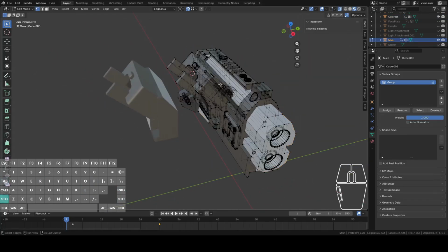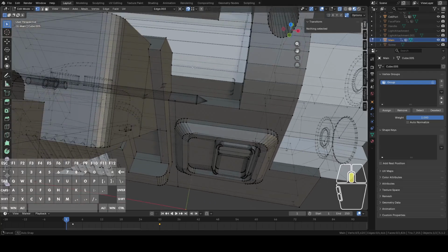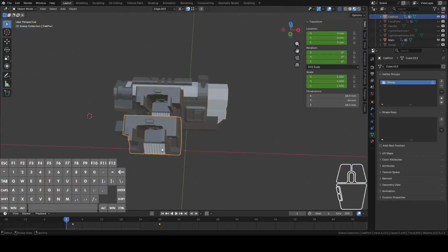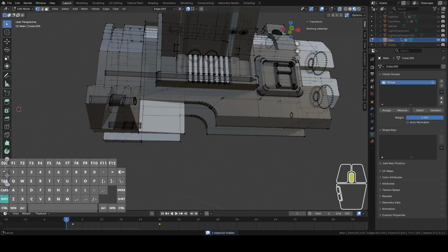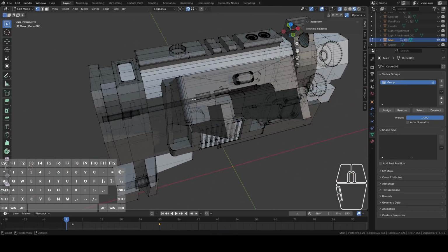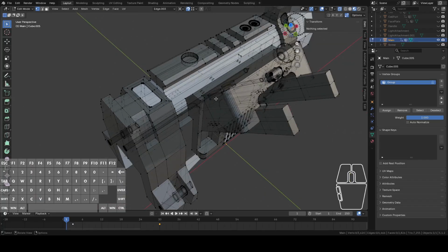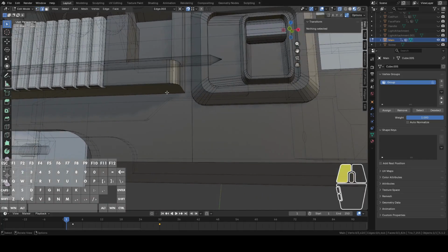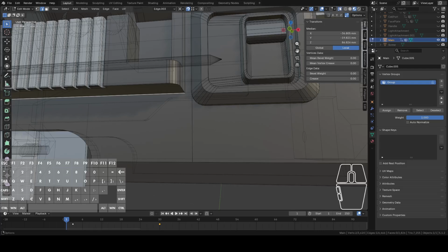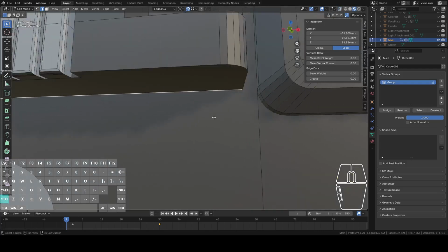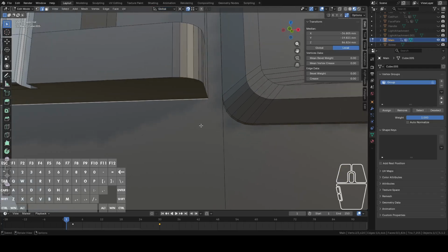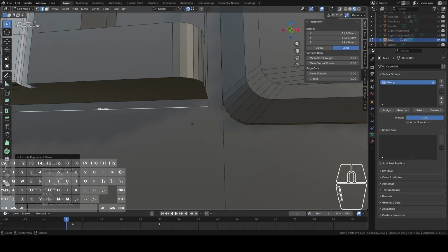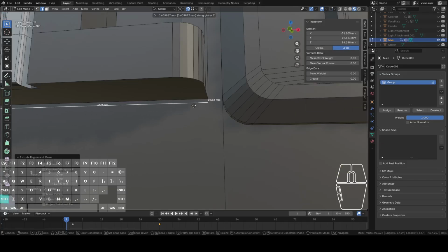Okay, so now for this one, in order for the cell port to actually fit in here, we're going to need to make a hole in here that's at least 0.5 millimeters wider than current. So I think just every angle will need to go out just a bit. So I'm going to start over here. Let's get back onto global. And I'm just going to extrude downward. Let's get our edge links back up. And get that close to 0.5, at least 0.5.